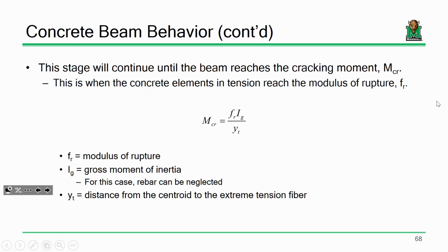So one of the first steps that we like to do in reinforced concrete design is start to ask ourselves, when does that philosophy become invalid? In other words, if concrete is a material that behaves poorly in tension, at what point do the regions in tension begin to experience cracking?